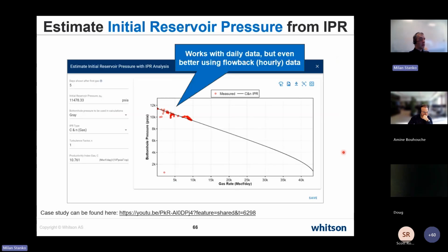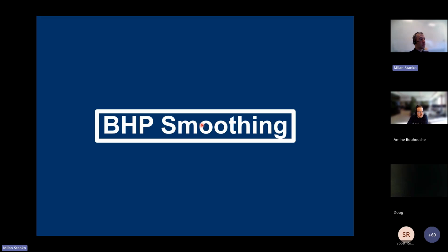Okay, of course, for them to fall on the same IPR, the reservoir pressure shouldn't have changed that much. So you should not use points that are, let's say, a month away or a lot of days away. If you use points which are hours or days within the month, that is better. Otherwise, the reservoir pressure starts to drop, and then they shouldn't fall on the same line.